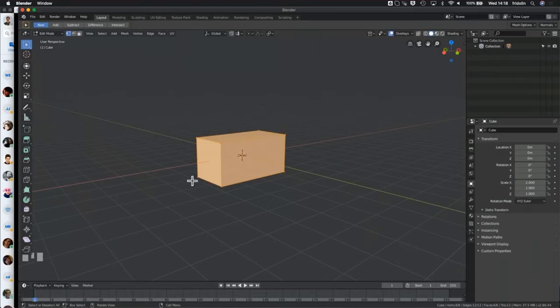Now, all of them are currently selected, as you can see by the fact that it's all shaded slightly orange. If I clicked on a particular vertex, then you see the shape actually turns grey, but the one we've selected is just highlighted orange slightly. So I can just left-click and select different ones like that. If I hold Shift and I continue clicking, then we are just adding more vertices to the collection. And similarly, if I hold Shift and I click on one that's already selected, it becomes deselected. So yeah, using Shift to add things to a selection is commonplace in tons of different software. I'm sure you'll have all encountered it before.